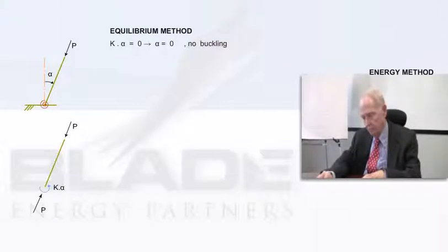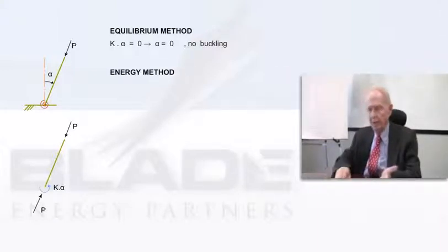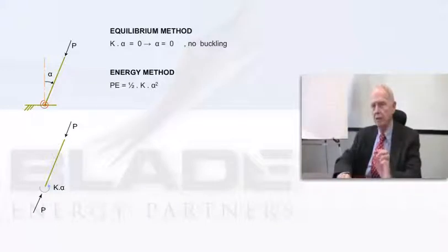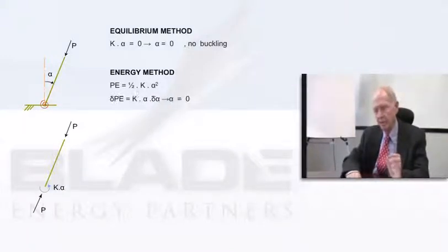In the case of the energy method, strictly speaking, there is no potential energy for a follower load. But this is a very degenerate case, and you can pretend there is a potential energy, because P does no work, and it's zero, so what do you care if it's dependent on a point?